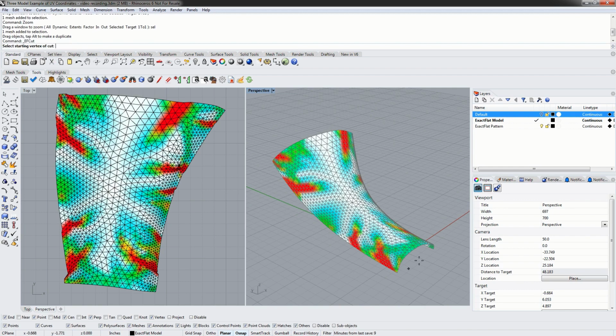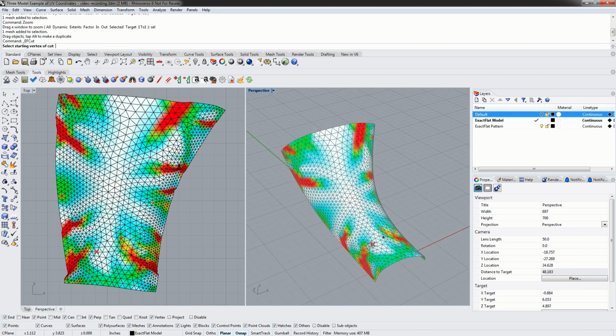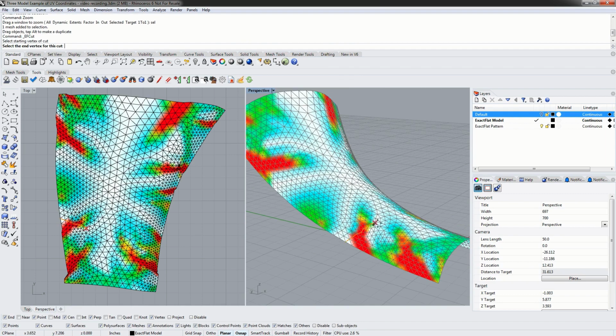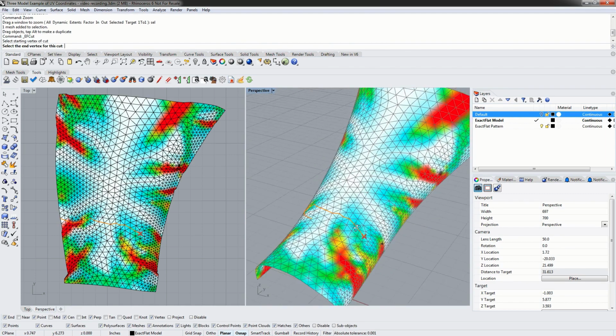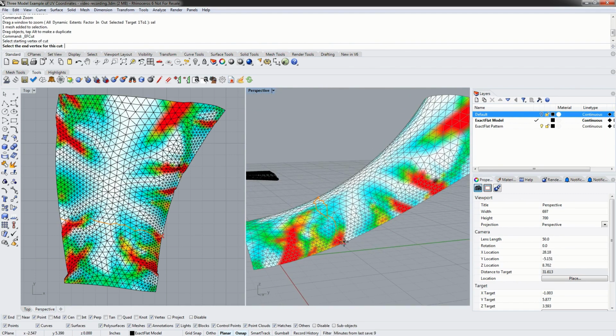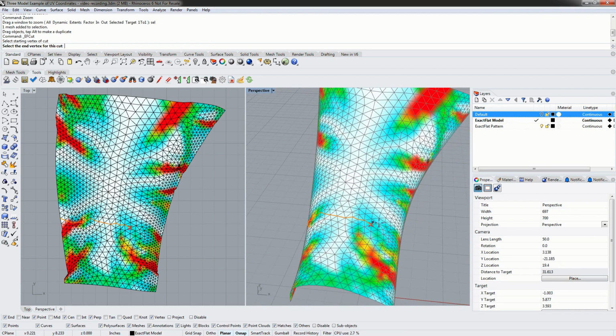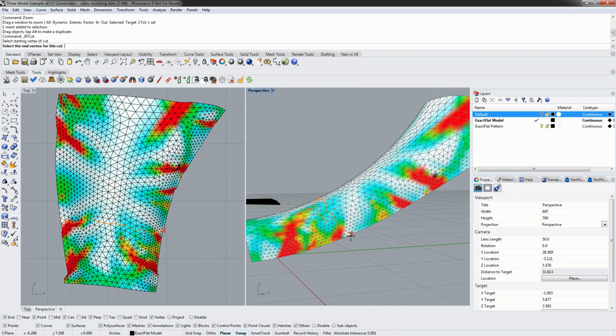cut command. The shortest path cutter works by allowing you to select a start and stop point for your cut, and ExactFlat will automatically determine the shortest path along existing triangle edges to form that cut. You don't have any control over where that path goes. However, instead of creating one cut from the start to the end, we can create multiple cuts across the path to create our cut profile.